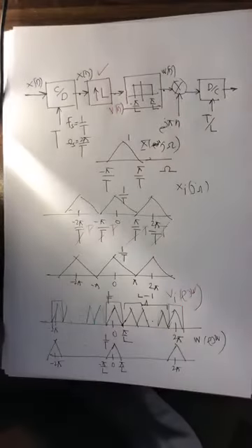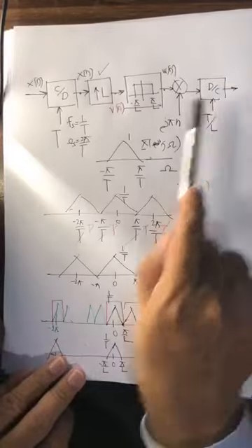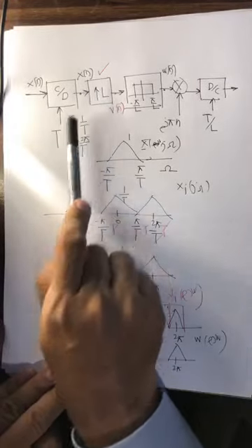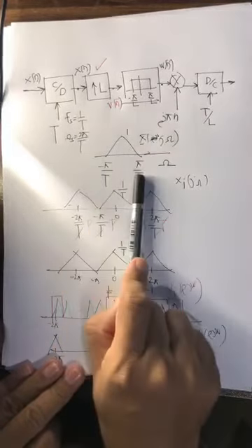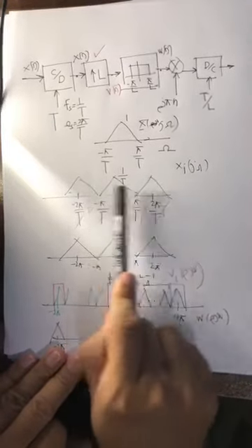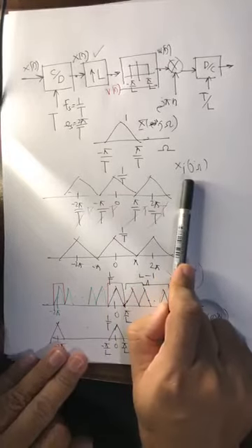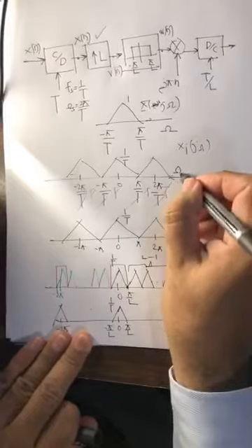You will be given the spectrum, and now you are asked to pass it through the system step by step. The first step is you pass it through a continuous to discrete time converter with sampling rate 2 pi over capital T. So this pi over T is telling me it will not alias, because the pi over T to pi over T copies are here. So this is my X j omega, still an analog signal with frequency still omega. We have done several of these.